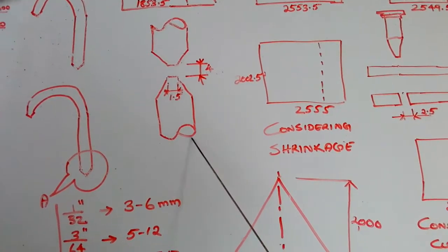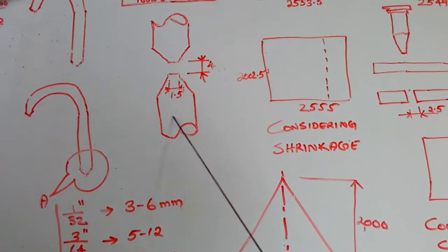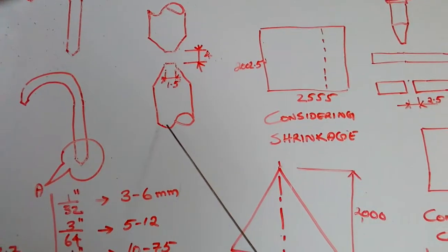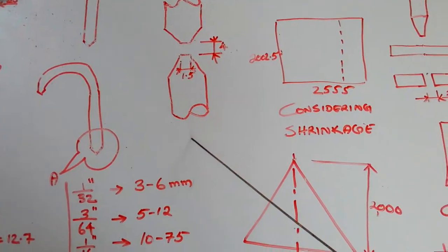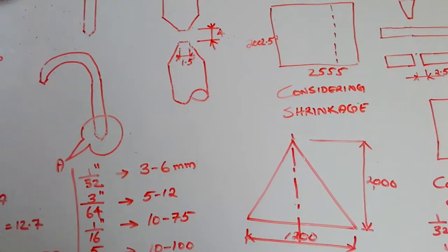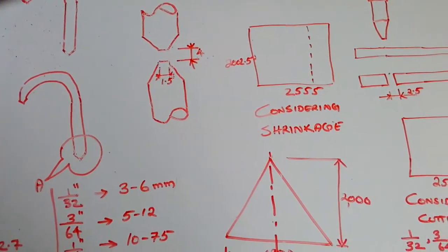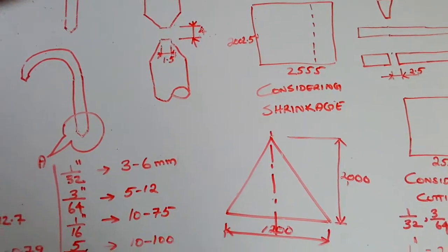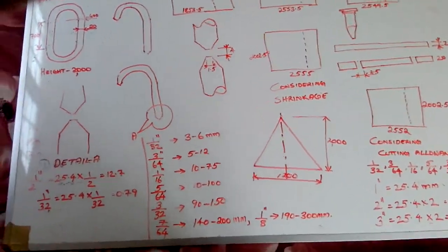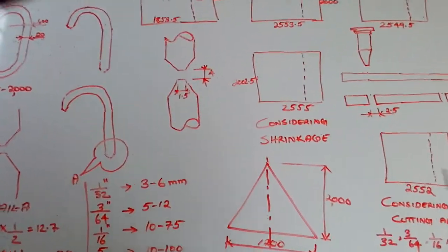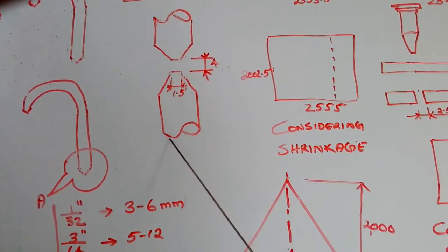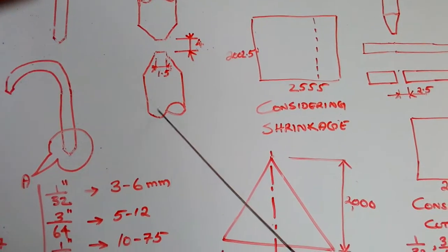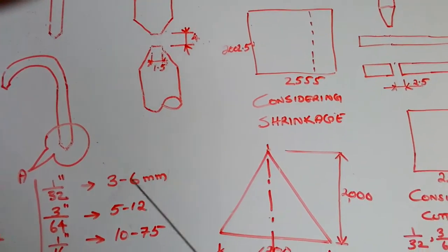What does it mean? It means this 20 mm plate starts from here, but it doesn't end here. It has more length. It is going more and more length. But we can't draw all of that on this paper or this whiteboard. There isn't enough place, so we draw this much only, from here to here. But it continues here. This indication means this job doesn't finish here, it continues.